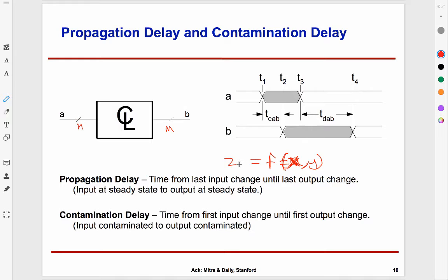So looking at this, I have a combinational logic with multi-bit signal A coming in. This piece of hardware is always monitoring those bits, and whenever any of those bits change, one or more of them, it conceptually recomputes immediately and creates something on the output. Furthermore, as we saw in the previous slide, since my output is multiple bits, it could be that some bits get known sooner, and other bits get known later.